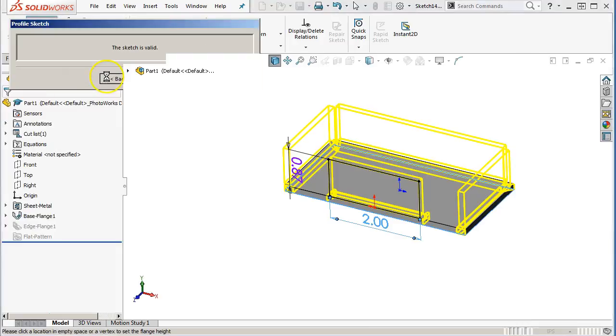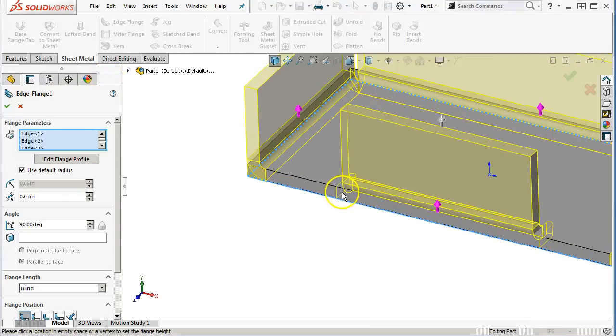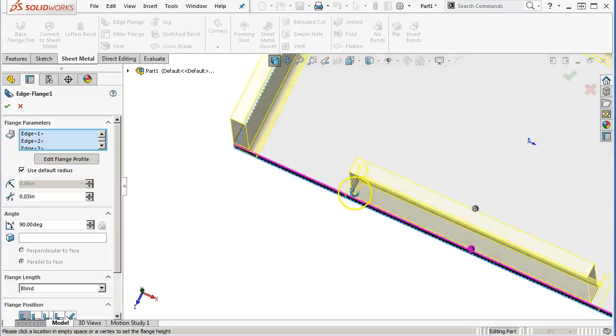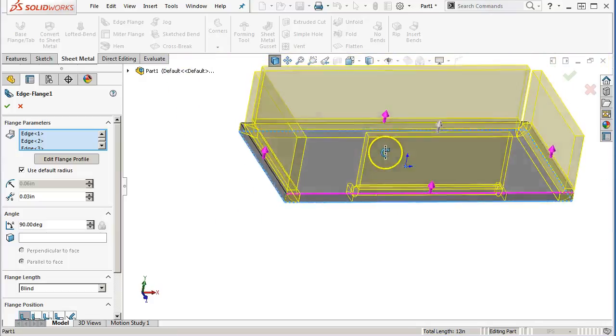I can go back, and that flange gets smaller, and because it's an interior, this is my obround or my tear. That's my relief type. Because otherwise, if I bend this up on an internal like that, it's going to deform all of that material up into that radius. So we have to have some mechanism to allow for that bend without interfering with the material to the side of it.